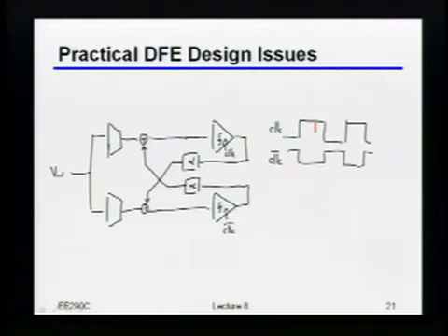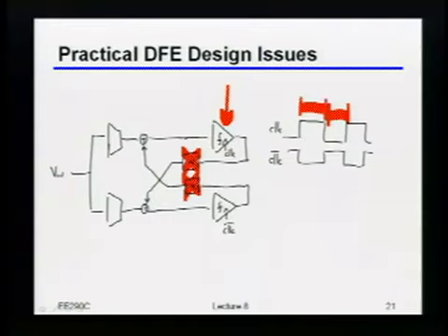Wait, what does this buy us again? Okay, so in this particular example, it turns out to not buy you anything, which is kind of why I did it this way. But imagine that I wasn't closing the first tap, right? So if I didn't need to do this, then now notice my comparator actually has twice as much time to reset itself, right? And in principle, if I was really limited by, let's say it was a CML comparator or something like that, I've also got twice as much time that I'm staying in the input sampling phase. Of course, that's when not closing the first tap, meaning unrolling the first.